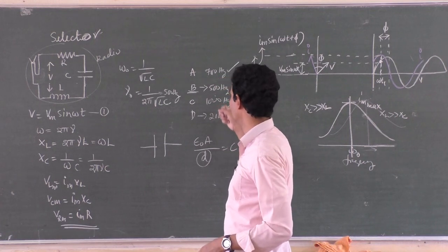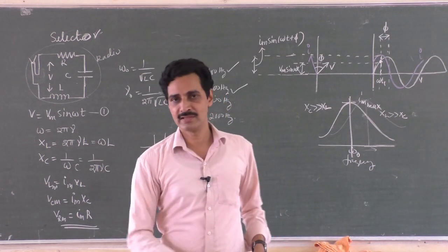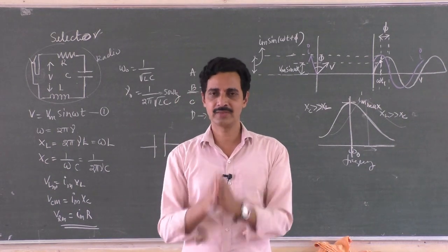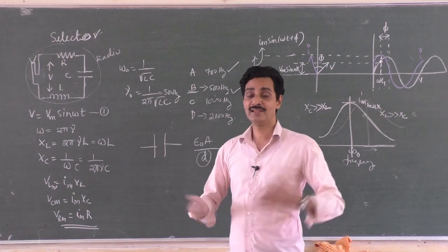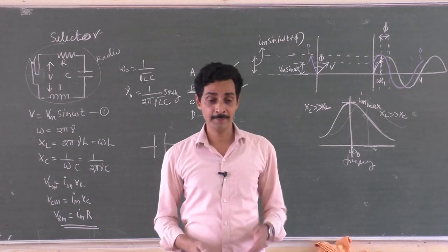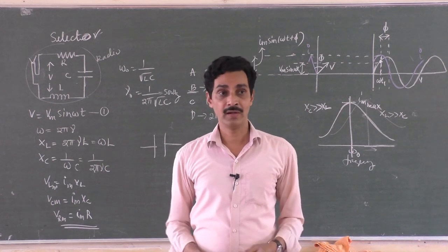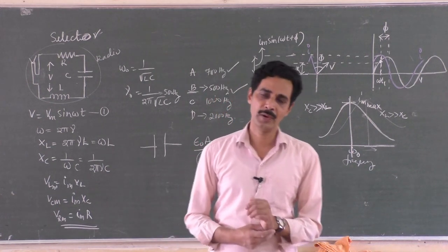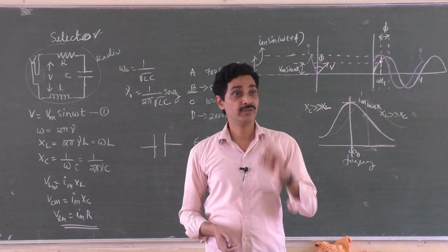Now you can't hear B, C, D. So by changing the capacitance value, by changing the distance between the plates of the capacitor, we used to change the resonant frequency and thereby hear different radio stations. So remember, if a radio is switched on, it receives all the signals from all the radio stations, but only one is picked up. Which is picked up?